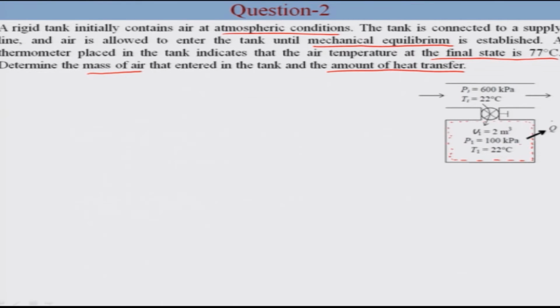So from the mass balance for this system, we get mass coming in minus total mass coming out of the system will be equal to delta M of the system. This is an unsteady state process, but we can analyze it as a uniform flow process since the state of the fluid at the inlet condition remains constant.